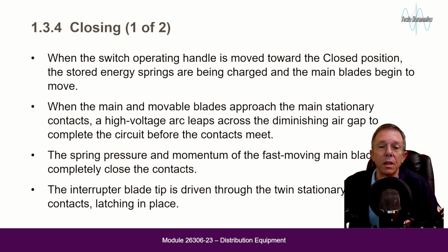The spring pressure and the momentum of the fast-moving blades completely closes the contacts. The interrupter blade is driven through the twin stationary interrupting contacts, latching in place.